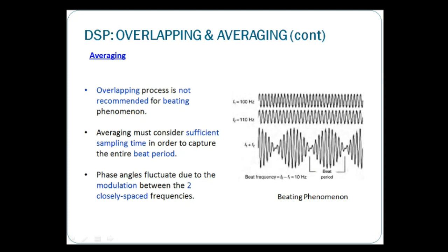One is running at 100 hertz, another one is running at let's say 99 hertz. Or one motor is running at 50 hertz, another one at 48 hertz. So they are very close. When they are very close, of course, this vibration will transfer from one unit to the other unit. So when you pick up, you will pick up these two very close frequencies.